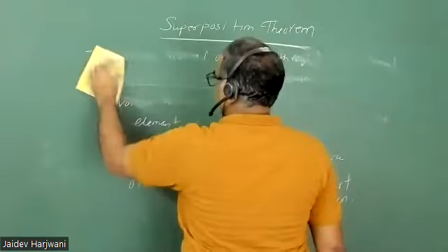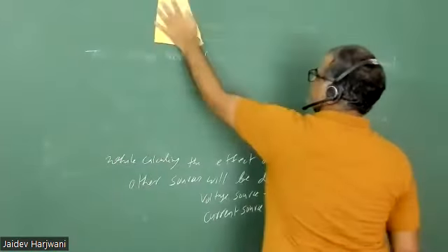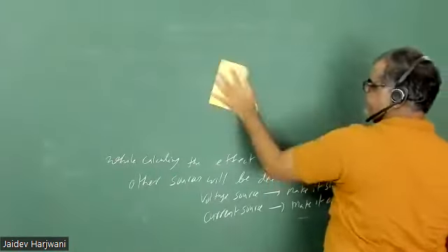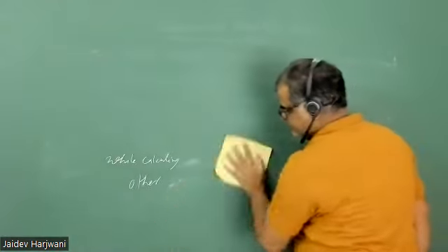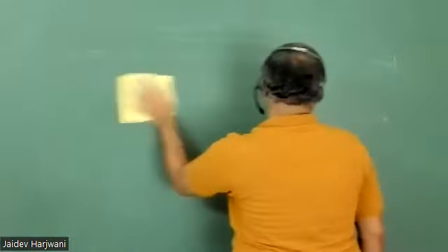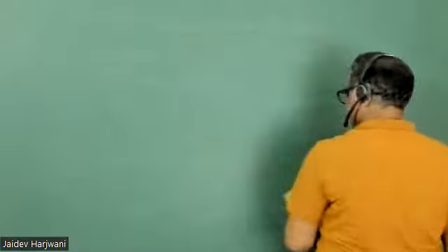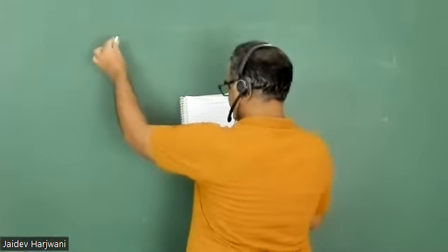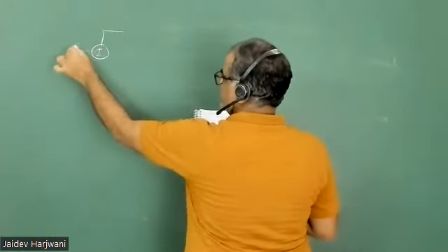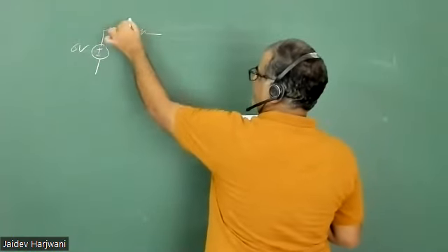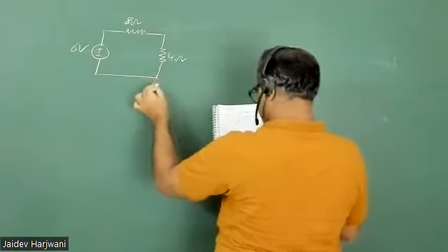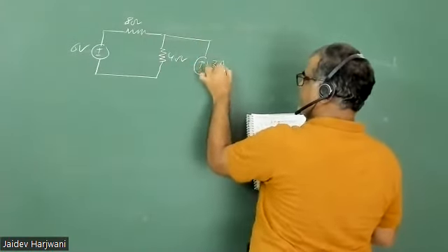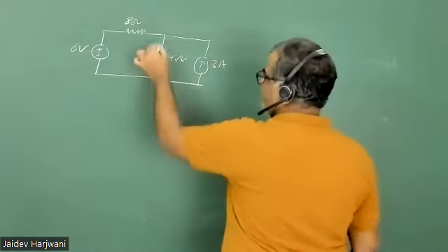So this is a very useful technique, okay, बहुत काम आएगी आगे when you solve op-amp problems. I'm giving you a question, we need to solve this one with the superposition principle. So we have 6 volt, we have an 8 ohm resistance, we have a 4 ohm resistance, we have a 3 ampere current source. Now we need to find the voltage across this one.